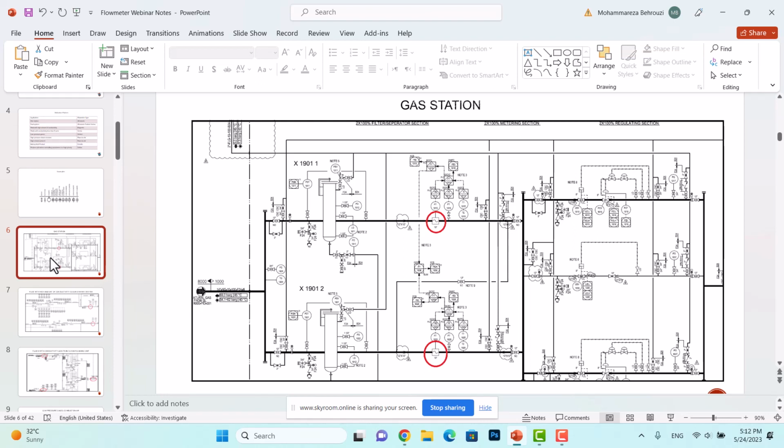At least in my country, it is not just a suggestion or advice. Now it is a regulation, and we have to abide by and follow such regulations. We are supposed to select ultrasonic flowmeters for gas stations because ultrasonic flowmeters have proved successful when it comes to the measurement of the gases to the inlet of the plant.